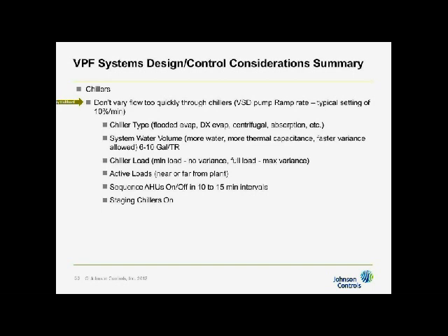If that's not fast enough, then you'll see your chill water fluctuate. This can all be done during commissioning. Your chill water will constantly fluctuate in temperature. It can't seem to settle down. Then you need to increase that speed. So change 600 seconds to 450. That's 15% per minute. On the other hand, if it's too fast, then you got to slow it down. Too fast is because you'll be going off on nuisance trips under low water temperature cutout.